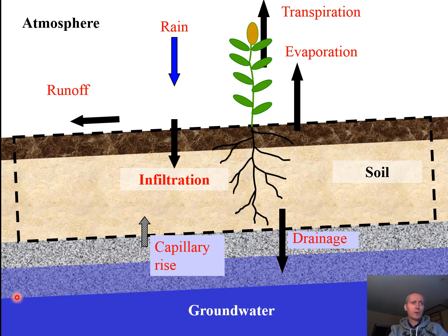If the incoming water flux is larger than the infiltration rate of the soil, a potential exists that water will be either stored at the soil surface or will flow along the surface as runoff. Infiltration therefore controls all the other fluxes of the hydrological cycle in terrestrial systems. In this and following podcasts, we will try to describe this process based on the soil physical principles that have been introduced previously.